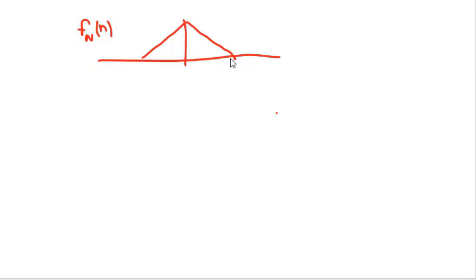Now in the question you are given the probability density function of noise f of n as from minus 2 to 2 and the amplitude as 0.5. Now when you transmit the symbol S0, which is equal to -1, then your R0 will be -1 plus N. So the PDF of the received symbol R0 will be -1 plus this probability density function of noise. Similarly, when you transmit S1, which is equal to 1, then your R1 becomes 1 plus N.